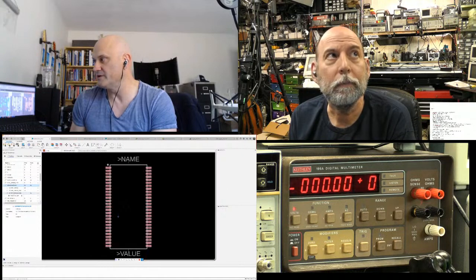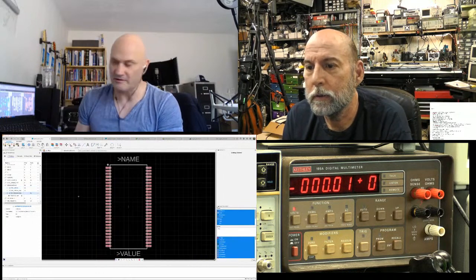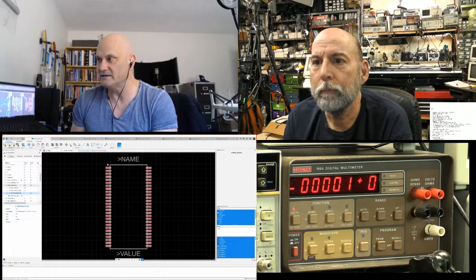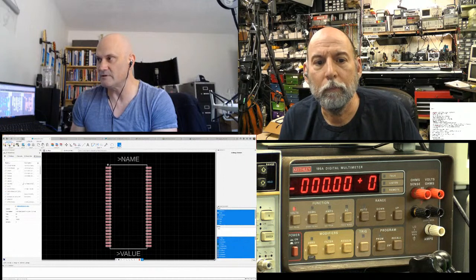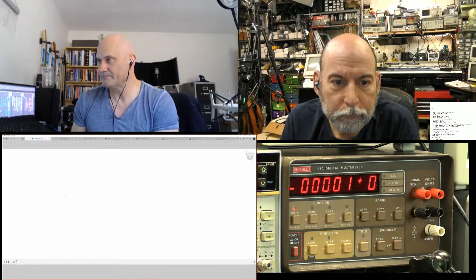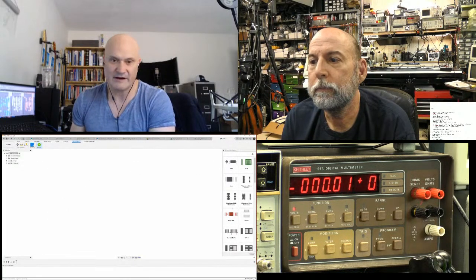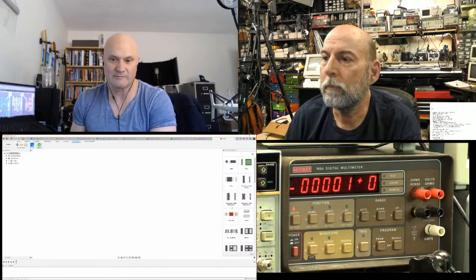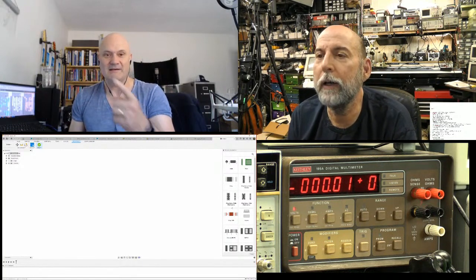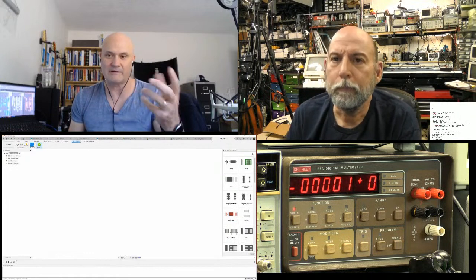So here's the other cool thing. I've got the component editor there. I've got the symbol editor and footprint editor, which people are very familiar with. But one of the other things I really love about this is the 3D modeling. If I'm in a library here, I can actually start with a package if I have a data sheet, and make a new package. And this puts me in the 3D modeling environment, but automatically loads this generator. So this is like an IPC compliant footprint wizard, but it doesn't just give you a footprint, it gives you an actual 3D model, not just a step model, but the actual timeline with all the sketches and extrusions used to build the 3D model, so you can change it or parameterize it.